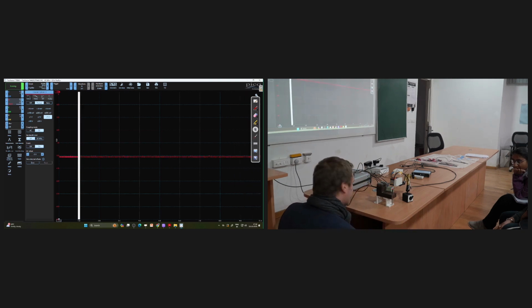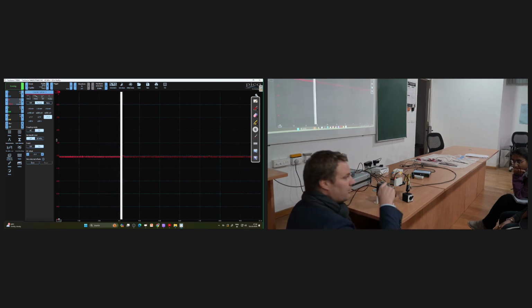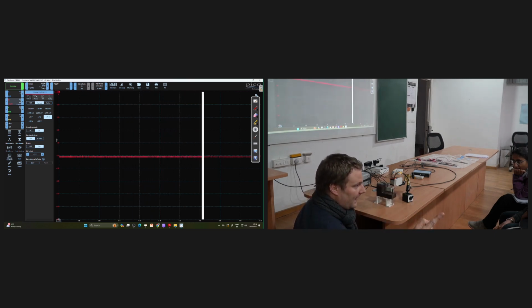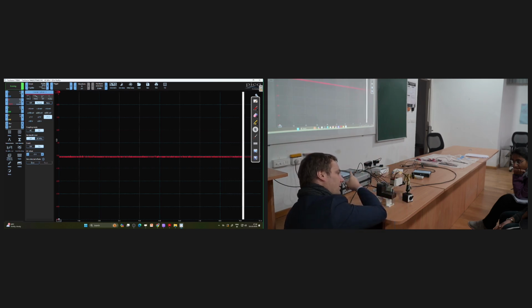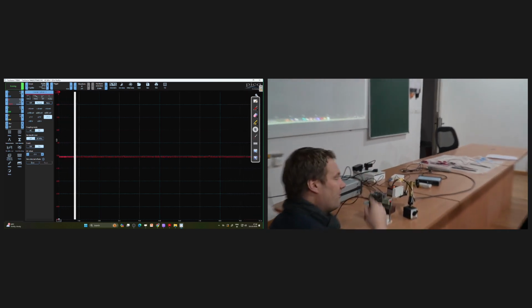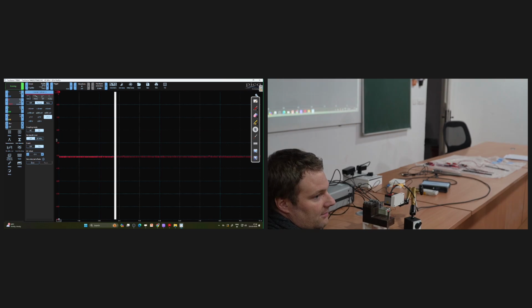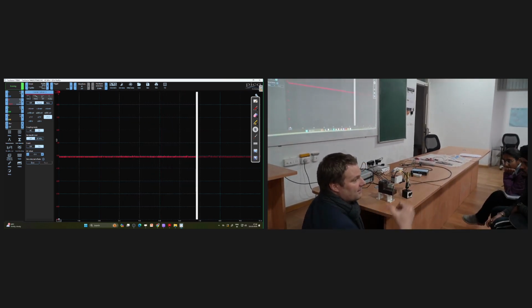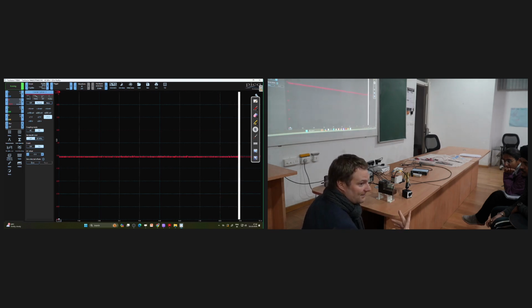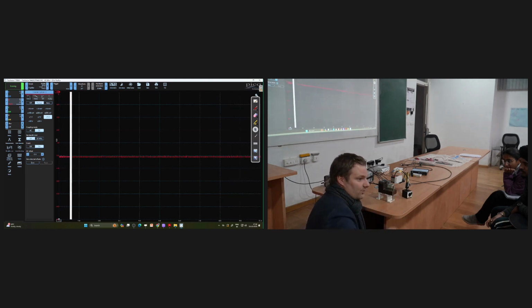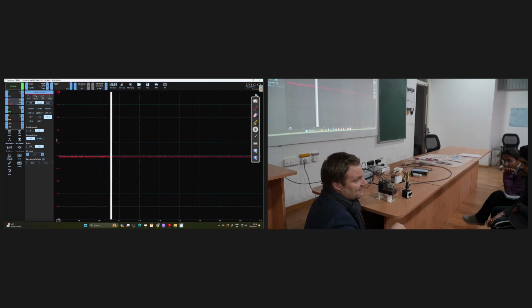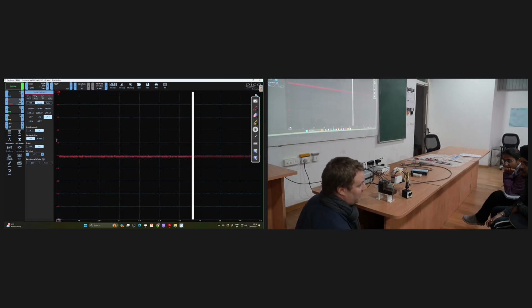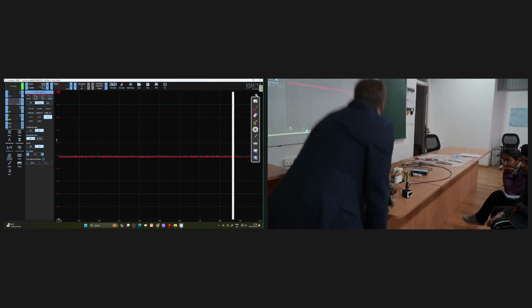So the next thing we do is a signal where we put first a high field on it, and then a negative field on it, and then a high field and a negative. So in the butterfly curve, or the butterfly diagram, we go from the left to the right, to the left to the right. And then what should happen ideally is that the elongation, which is the y-axis, does exactly that. You should see the butterfly curve in the end. So let's hope that works. It's always a thing with experiments.